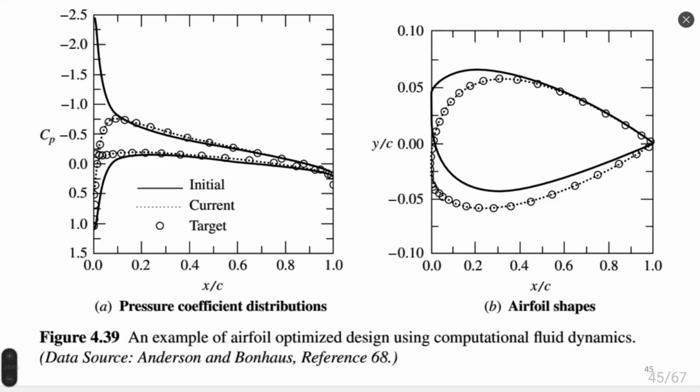Of course, we are trying from aerodynamic point of view to find lift to drag maximum. This is our target, but we don't know how the points will be distributed in space. If we knew our target in space, we would not provide any optimization. We would just simulate one time. So in terms of pressure coefficient distribution and in terms of shape of airfoil, we can find significant difference between initial geometry and final geometry of simulation.